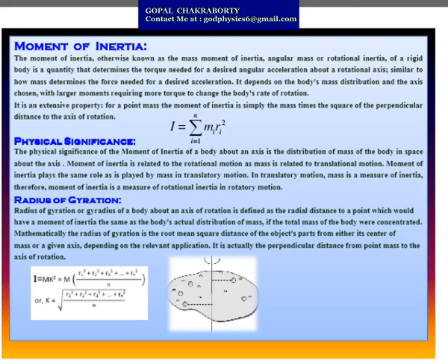It is actually the perpendicular distance from the point mass to the axis of rotation. So, in formula you can write I equals m k square, where k equals the square root of r1 square plus r2 square plus r3 square up to rn square, divided by n, if we consider n number of particles. This value is a constant k, and that k is called the radius of gyration.